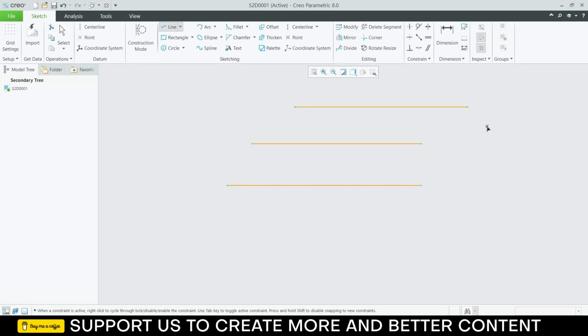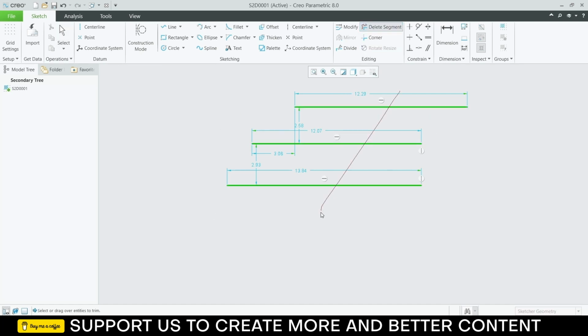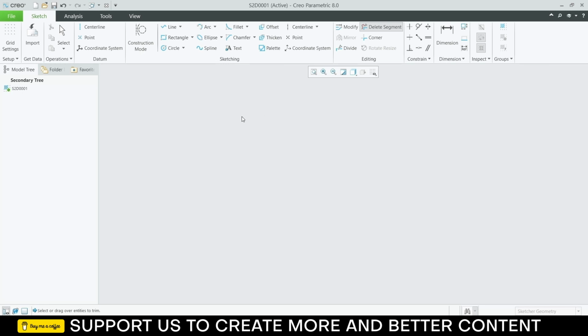And if I click again, notice I got the dimension of the lines. Let's try one more time so that you can understand, as I assume that you all are beginners and have no clue or idea how it works. So I will draw a line. Now I want to end this line command. If I press the middle mouse button once, it will end the line command. But if I press the middle mouse button again, it will give me the dimension of it. So I hope you understand how this works.